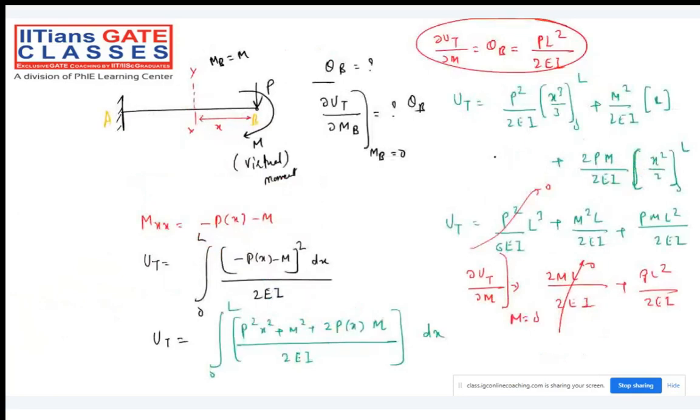If they want to throw a difficult 2-mark question, they can just throw that question, simply a problem. But in the cantilever, there is no difficulty. Even in the cantilever, if I change the loading condition like this, EI and 2EI, nothing matters, because at the day end, the slope is 0, and we are taking the reference from here. Happily, we can solve the deflection anywhere. Cantilever, no difficulty. But the moment I change the beam itself from cantilever to simply supported, everything will be changed, right?